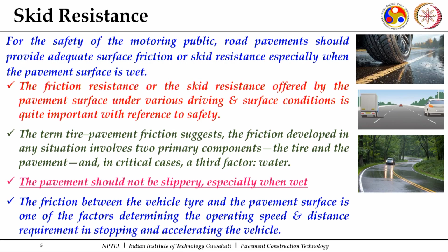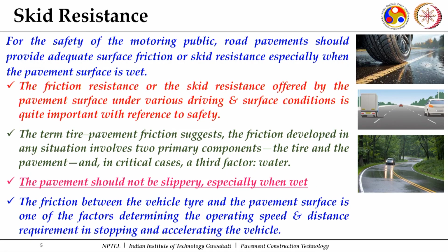Now, specifically when it is related to road surface, the safety of the motoring vehicles or the users is highly dependent upon the skid resistance or the frictional resistance of the surface, and this becomes more challenging specifically when the pavement surface is wet, because this frictional resistance gets significantly reduced in the presence of water.